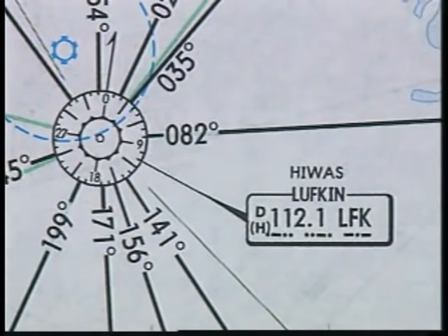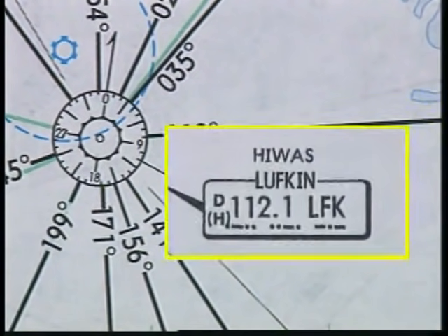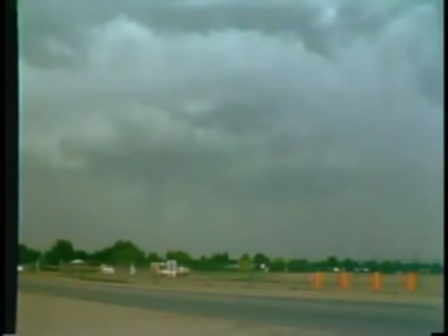Availability of another type of en route weather service is shown by a HIWAS designator. HIWAS stands for Hazardous In-Flight Weather Advisory Service and is continuously transmitted over the VOR frequency. HIWAS broadcasts contain weather advisories, including severe weather alerts, SIGMETs, AIRMETs, and urgent PIREPs.